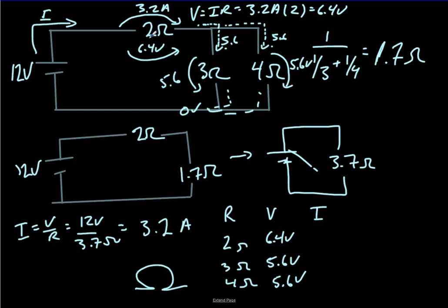you'd have to reanalyze the circuit. Like if I put a 10 ohm in here instead, yeah, that has lots of effects, right? So there's 10 ohms here. Now all of a sudden we've got an 11.7 ohm circuit. So what does that do to current? Well, it drops the current.